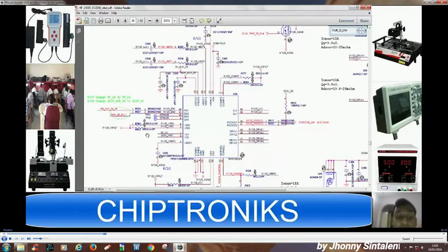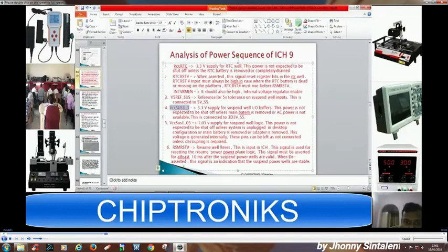It would come from a gate IC, A plus B equal to Y, and where is B coming? B is coming from the IO regulator. So we have to test the IO regulator, and how is the regulator generating B? We have already checked it. It is interacting with the EC BIOS, getting inputs at the IO controller, and then generating S5 enable, and then becoming this signal. So by checking the motherboard in this sequence, we will not leave any important things.